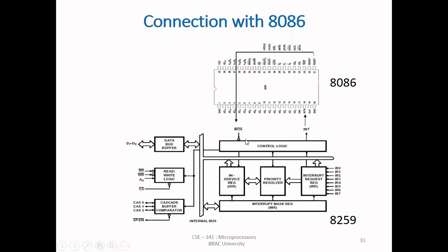In the case of the first interrupt acknowledgement pulse, it will set itself according to whatever configuration we have sent through the 8086, and in the second INTA pulse, it will send the 8086 that type of interrupt through this data bus. The interrupt type that is sent to the 8086 is determined by the IR input that received an interrupt signal and by a number you send the 8259A when you initialize it.